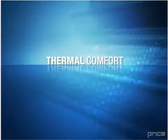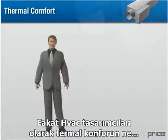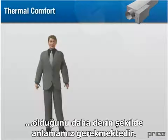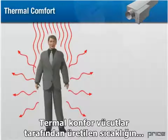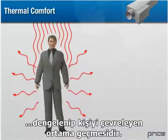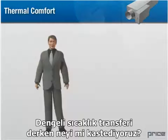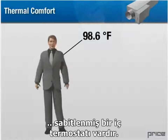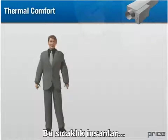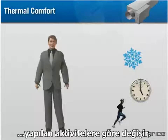Thermal comfort. We now know what human comfort is, but as HVAC designers we must understand more specifically what thermal comfort is. Thermal comfort is achieved when heat generated by the body is balanced and transferred to the surrounding space, and the occupant is not aware of this process in any fashion. What do we mean by a balanced heat transfer? A healthy person has an internal thermostat that is on average set to 98.6 degrees Fahrenheit. This temperature varies slightly between people, seasons, time of day, and what activities they are doing.